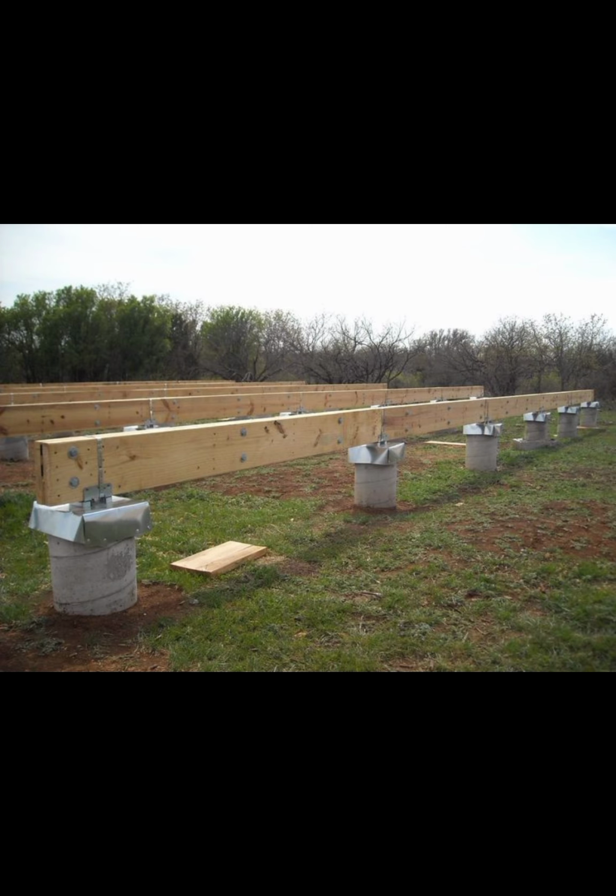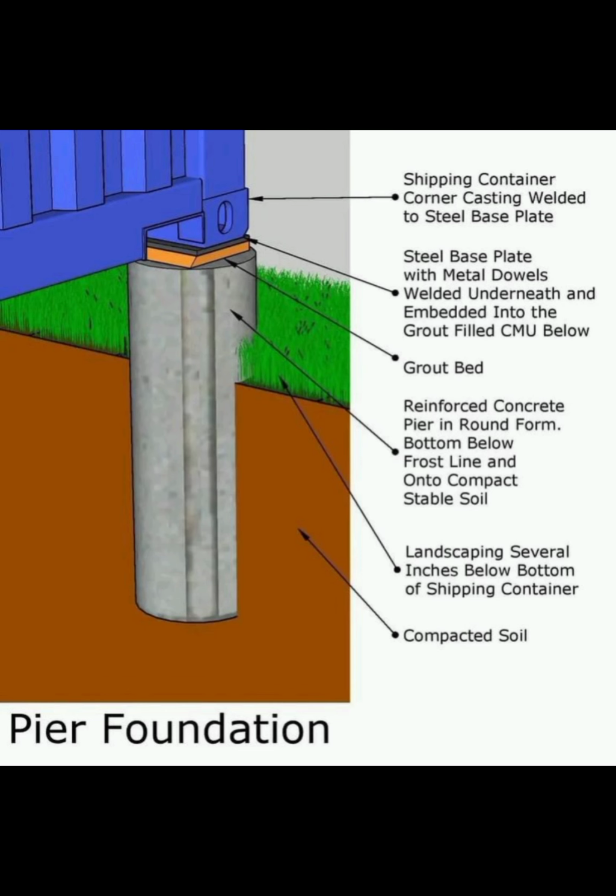So the difference between the pile foundation and the pier foundation is that the pile foundation goes much deeper till it reaches a stable layer, stable strata, or a rocky layer, something that can hold the structure. If not, they continue digging, they continue drilling, but the pier is shallow. So there are many more differences between all these types of foundation, but these are just the basics.